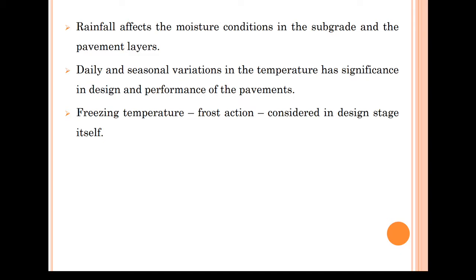Then when the temperature goes to a higher side, the ice formed reduces into water again, and hence a void is created. Due to this creation of void, there are chances of cracking in the pavements, and also chances of deformation when loads are applied on that pavement.